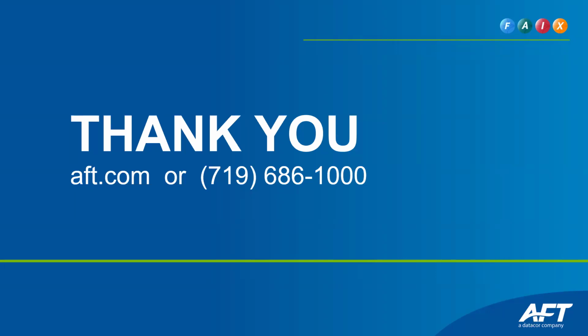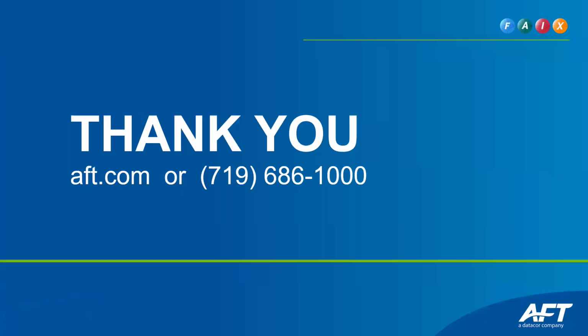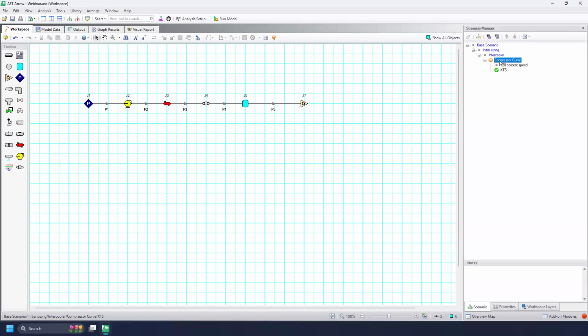Graph results show the static temperature decreasing along the pipe from the intercooler to the tank. However, it looked like the workspace results for the tank show the temperature above that of the intercooler outlet. Is there a setting that's causing this discrepancy? Yeah, so that's not because of a setting. So like this being 205 degrees and this being 200 degrees, the reason is because of the energy equation.